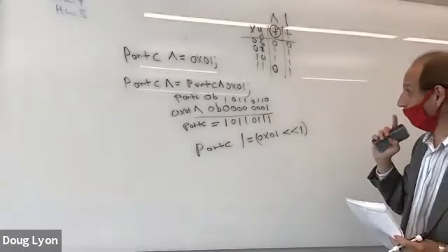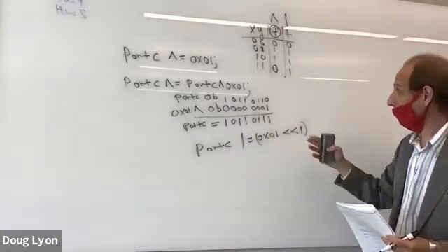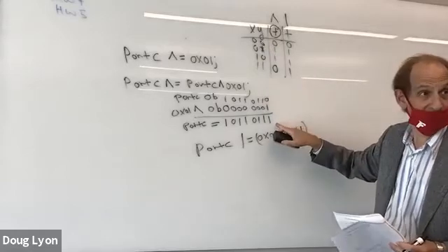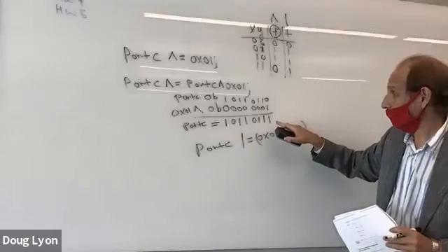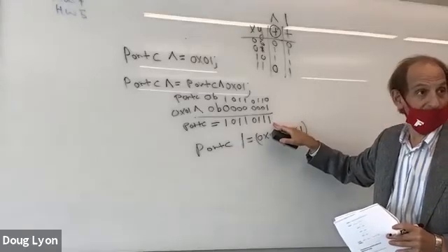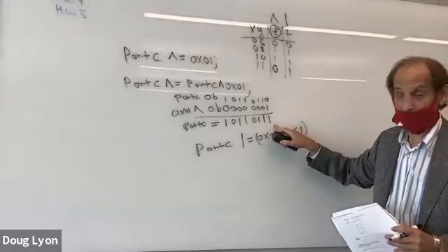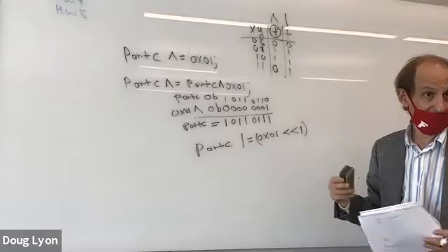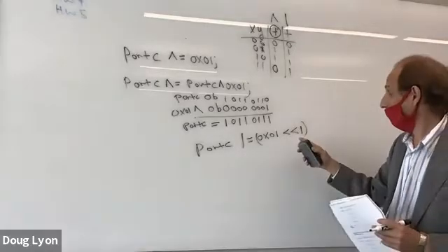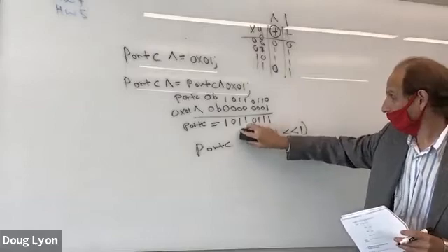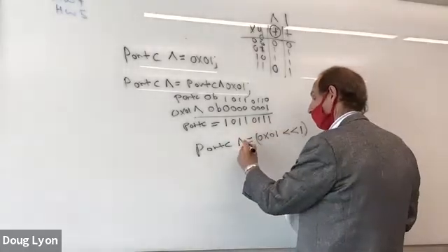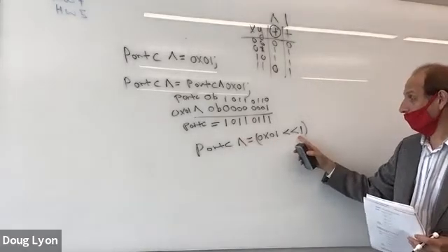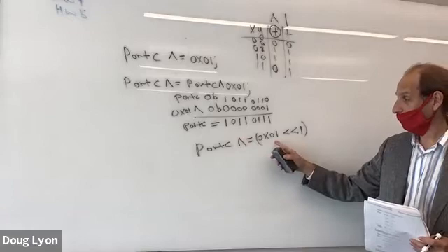But by switching that one thing, I have taken the 0 and turned it into a 1. If it were a 1, it would turn into a 0. So this has the effect of toggling the least significant bit. So that does a toggle. And if you wanted to toggle not bit 0, but bit 1, then you could do this operation, and now you can toggle bit 1. In fact, you can toggle any bit you like using the shift with the 0x01.